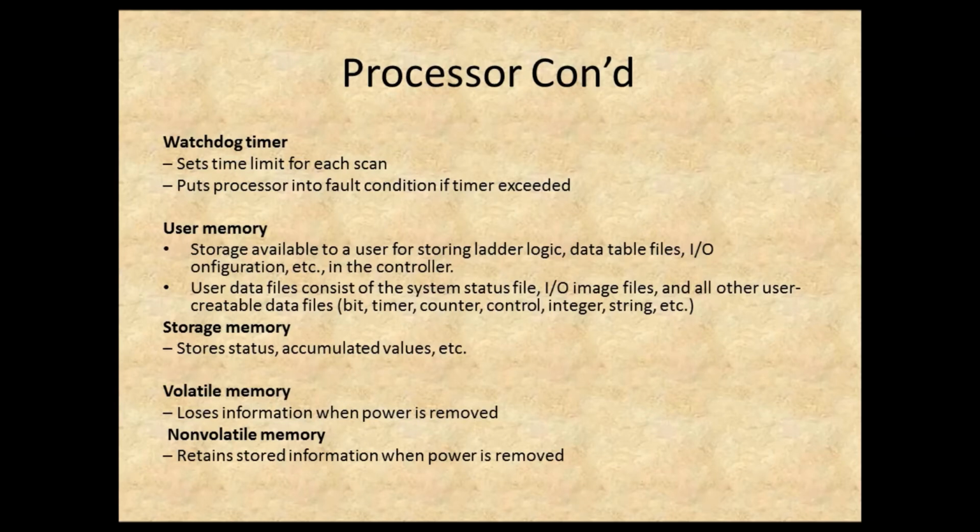Some processors have a watchdog timer, which sets time limits for each scan. And if one scan takes longer than the time limit set, it will put it into a fault condition.